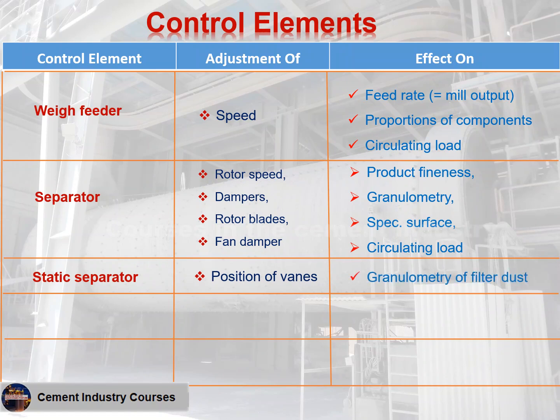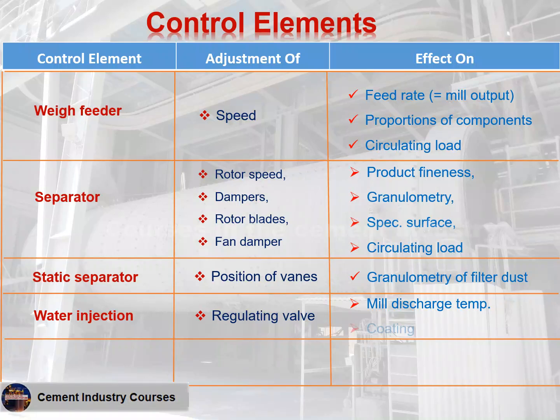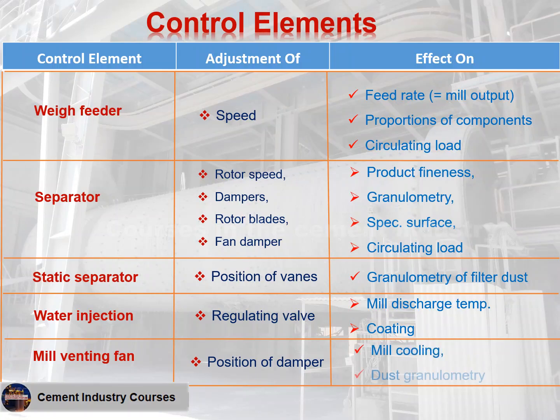Control element 4. Water injection. Adjustment of regulating valve. Effect on mill discharge temperature. Coating. Control element 5. Mill venting fan. Adjustment of position of damper. Effect on mill cooling. Dust granulometry.